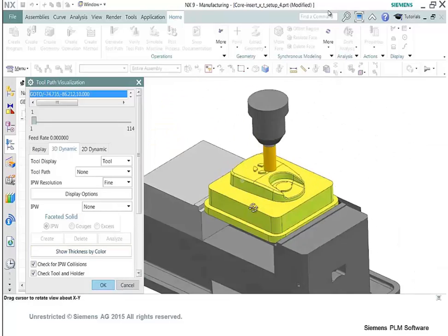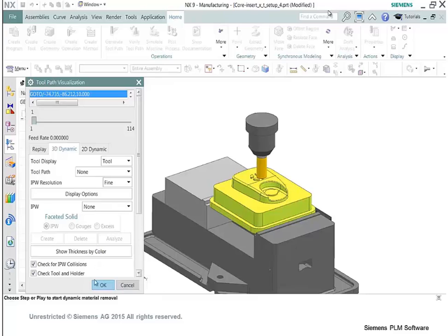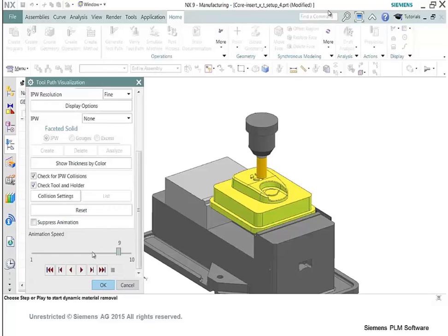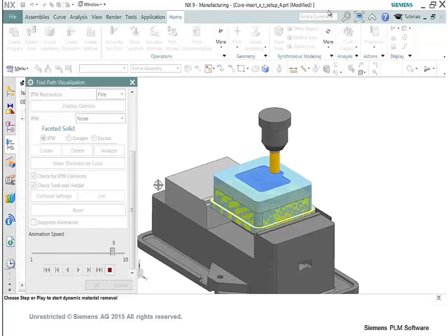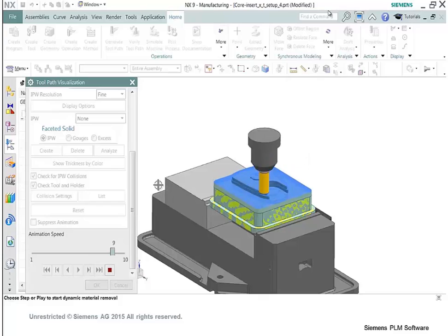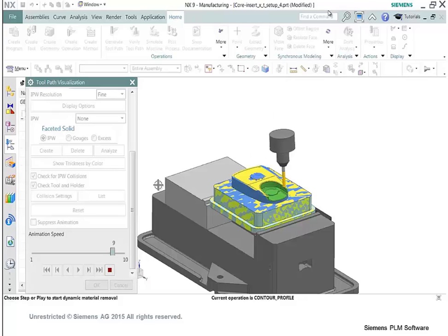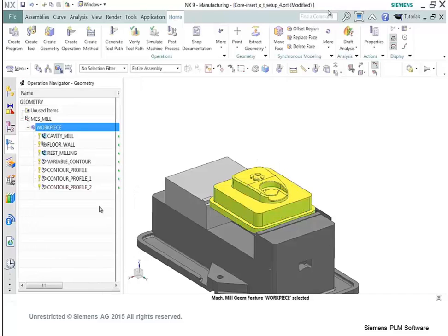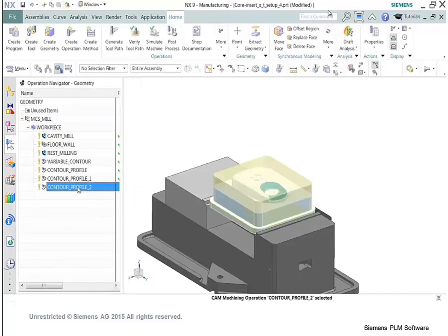And here, let's go back and take a look at it. Let's say in 3D. All right, and there we go. We're going to clean off all of our stock blank. That was our cavity mill. There we did a rest mill in the front. And the only thing we forgot, we cleaned up that side. We didn't do our radiuses around the outside, and we didn't clean up the flat floor up there, but we easily could do that too.